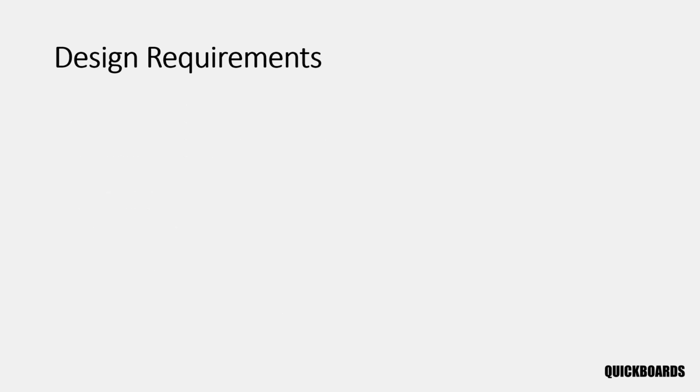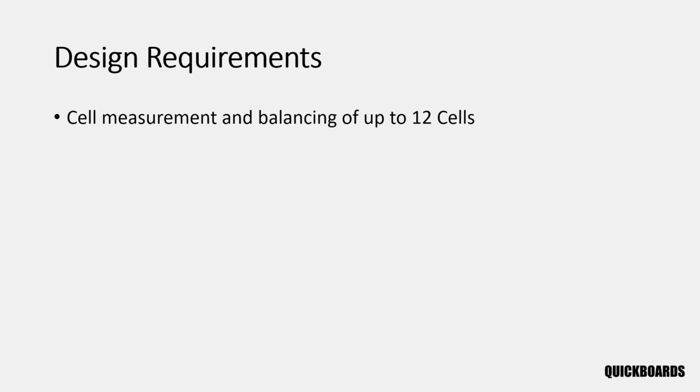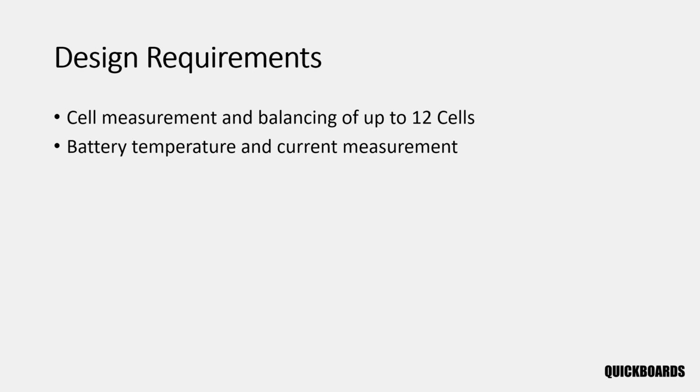Next, we'll develop a set of requirements to guide our battery management system design. It needs to measure each cell's voltage and balance all 12 cells to maintain consistent charge levels. It must also measure the total pack current and monitor the temperature of each cell.